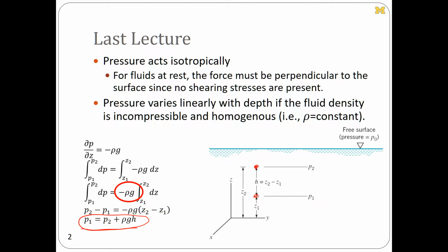Okay, so we extended that concept into that of manometry, and hopefully you went ahead and did some of the supplementary reading on different types of manometers. But the gist of it was that for a fluid called a gauge fluid with a known specific weight or known density, the gauge pressure, or the pressure of one point relative to the atmospheric or reference pressure, can be read or equated simply to the difference in the height of column, or the column height of the fluid on two different branches of the manometer.